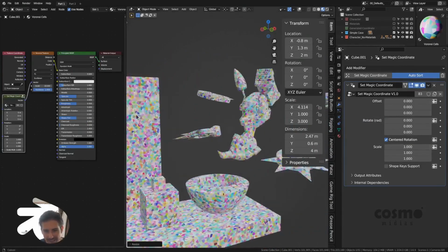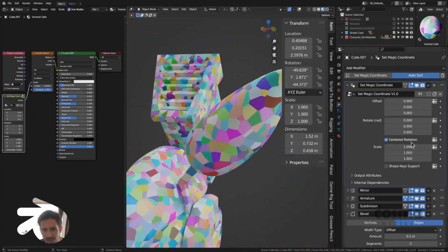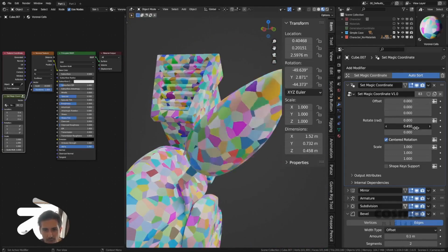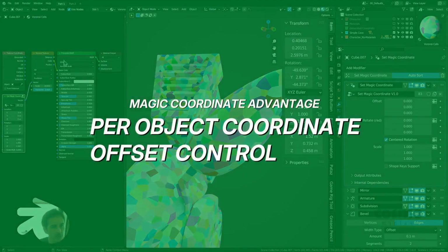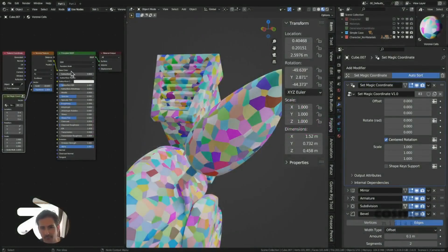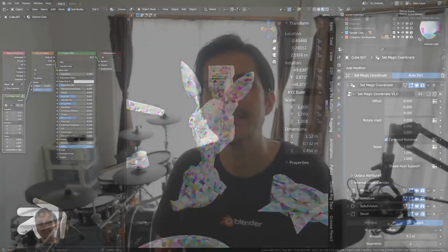That's the point. And also it's going to help you offset your texture for specific positions if you want. If you want to slide or rotate your texture, you can do that without forking your material into a new one, which prevents you from having tons of redundant materials in your project. It's very important. But yes, there is always a but. Nothing is perfect in life.